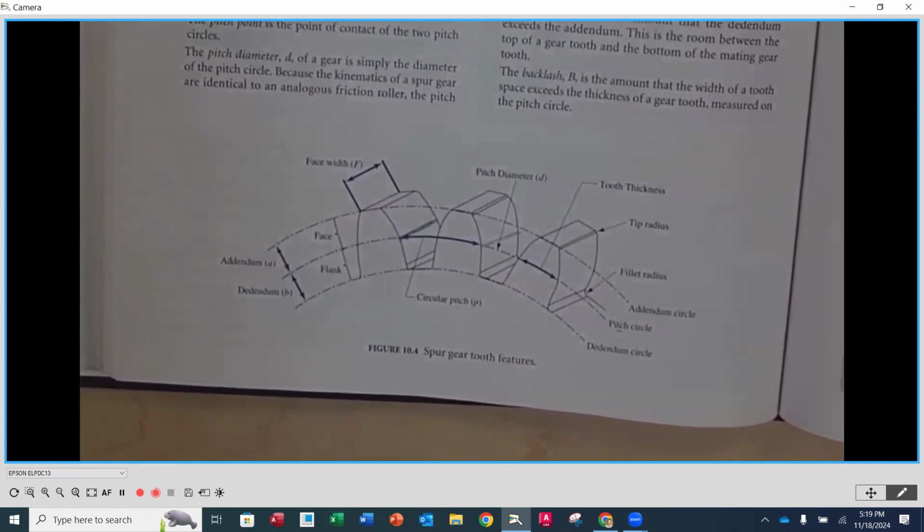You're going to find out in machine elements that teeth are going to experience two types of stresses. Pitting stress, where one tooth hits the other on the surface of the tooth. And then there are also bending stresses that occur. All of those happen right at that pitch diameter, okay? Because that's where the point of engagement is.